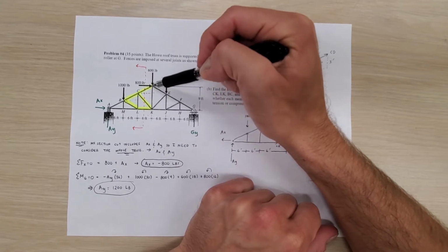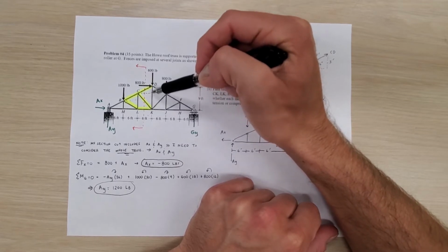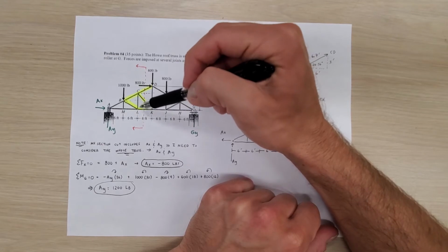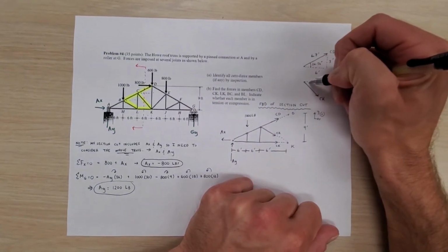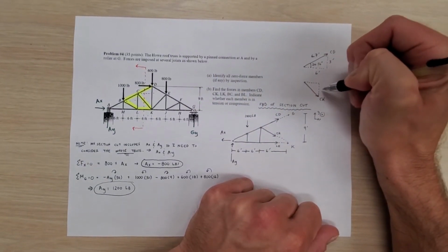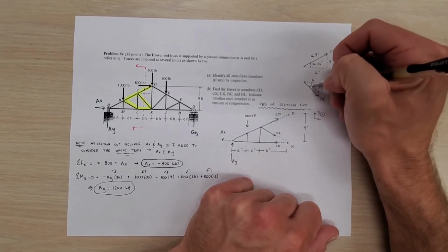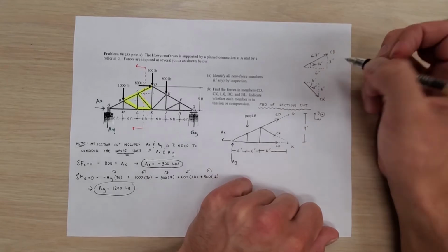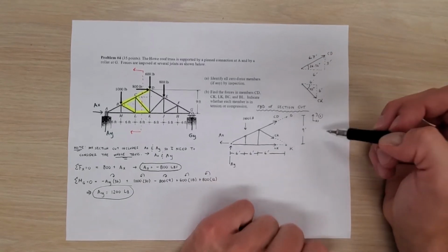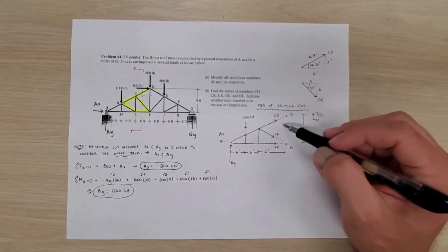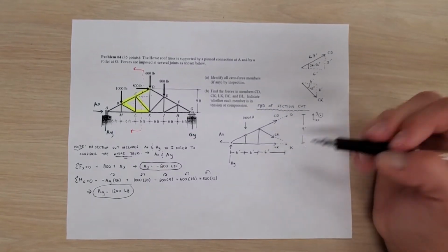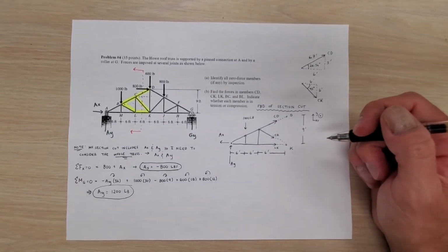So if this height here is 3 feet, then this height here is going to be 6 feet, and we know that the width is also 6 feet. So we get a little bit lucky with CK, and we know that the height is 6 feet, this is 6 feet, so I don't use similar triangles here. I realize this is a 45-degree angle, and I'm going to use that as we move forward. So I won't draw that on the free body diagram. I'm going to include that right there. That way it should be set up pretty good.